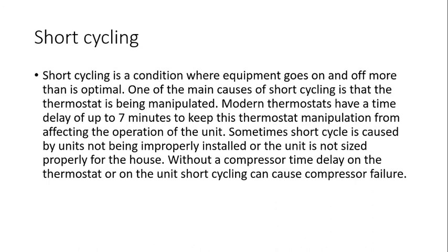And what I mean by this is, think about riding a bicycle. You're at a standstill and you start riding your bike on level ground. It's easy to start pedaling and get moving. But if you're looking at a hill with an 8 or 10% grade and you try to get on that bicycle and start pedaling from a stop position uphill, it's very difficult. Well, that's what a compressor goes through. When a system shuts off, for about 5 minutes, that pressure is not equalized. The high side or the outward side of the compressor has a lot of pressure. So now that compressor's got to start pushing against stuff right away. It's difficult for it to do and can cause failure.